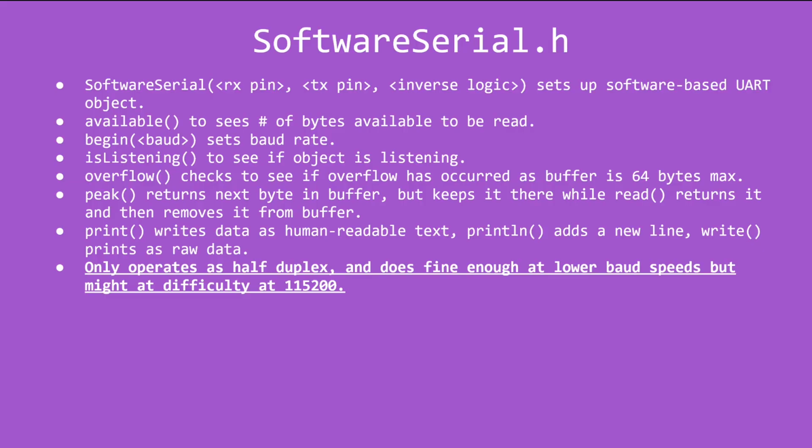Keep in mind this only operates at half duplex and it does fine enough at lower baud speeds. I usually start at 9600, and if I need faster, then I might inch it up there, but it might have difficulty at 115200. Your mileage may vary.